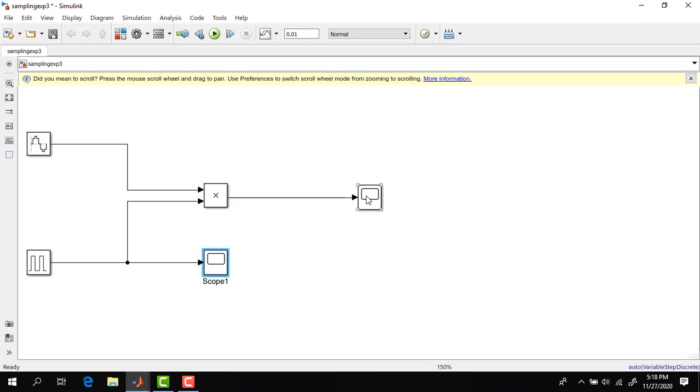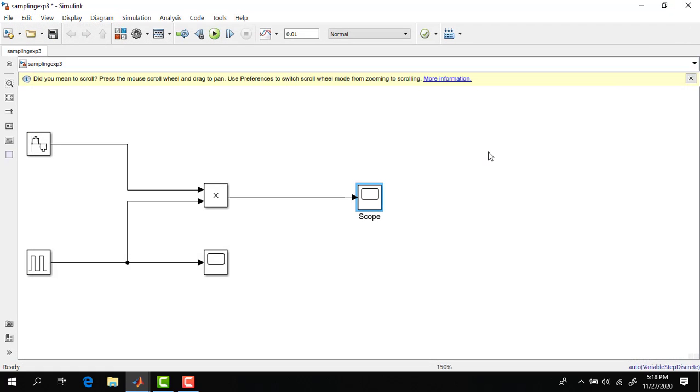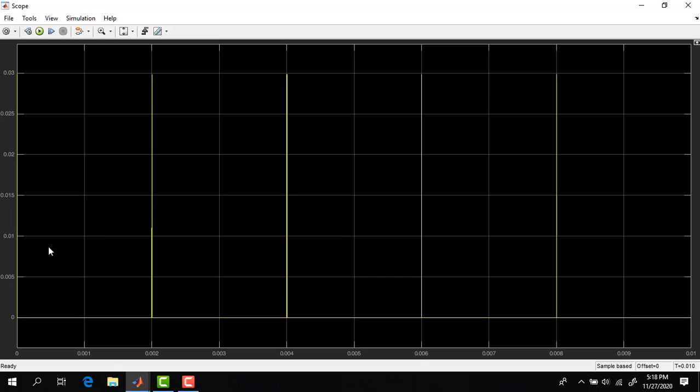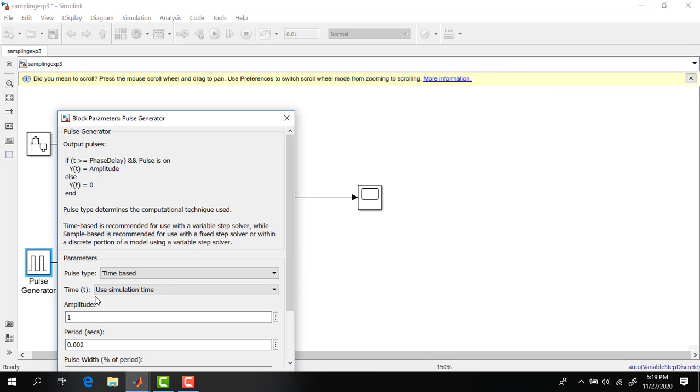So it's similar. Let's see the sampled signal. You can see in this particular case, the sampled signal doesn't correspond to the continuous signal at all. You can see from this sampled signal, you can never say that this came from a sine wave. Never. Even by naked eye, you cannot say this has even a slight possibility of coming from a sine wave. No possibility at all.